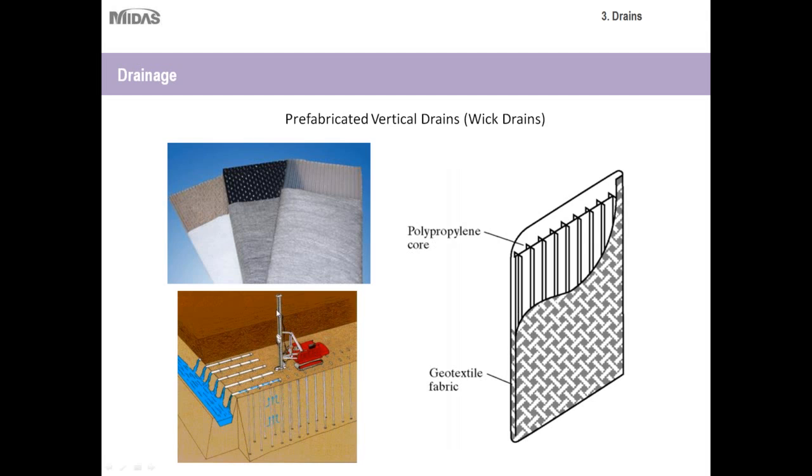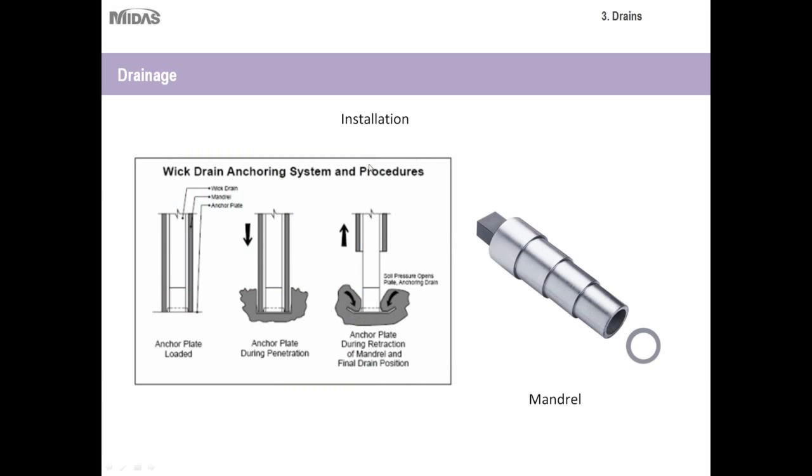You have an auger, or a drill, that will empty out these long vertical areas. But as this drill is working, it'll also insert these drains one by one. And as you can see, as the water is drained out, it's channeled out through these tubes here. So let's get a better view of what the installation process looks like. This is a side view of the installation process for PVDs.